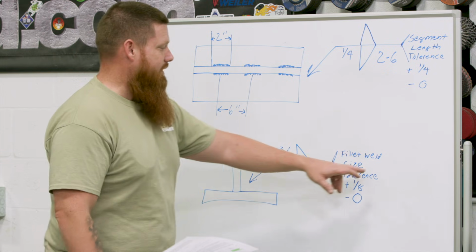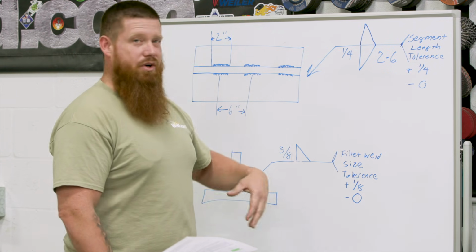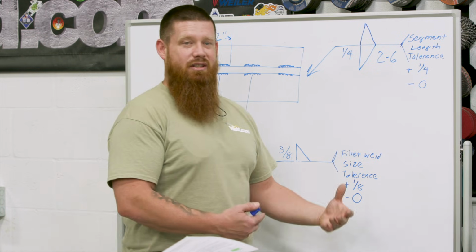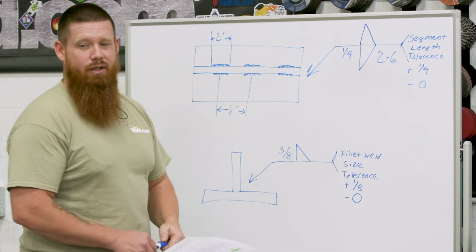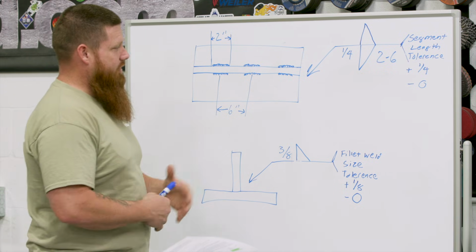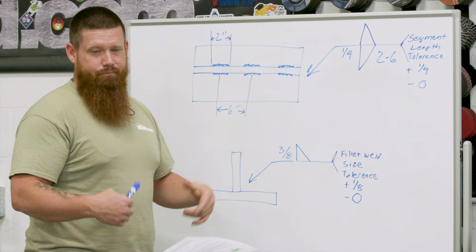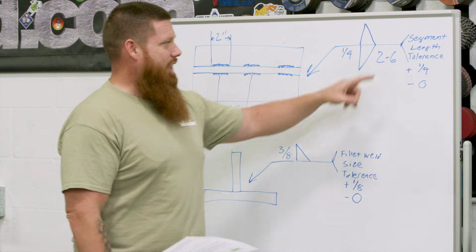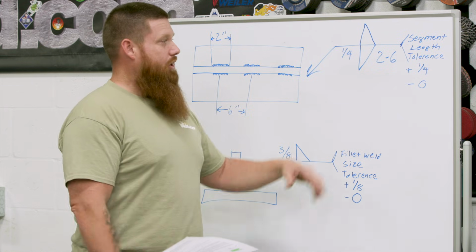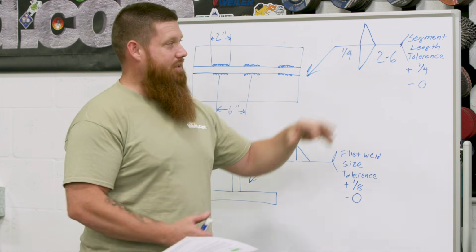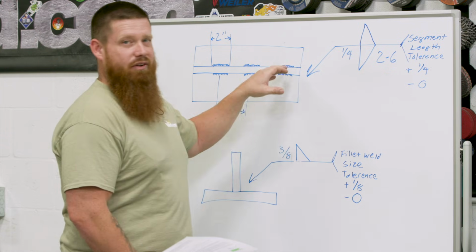So that's pretty much tolerances. They're going to be listed out in the tail. Remember, the tail is where we're going to find special information or additional information that they don't have an appropriate symbol or supplementary symbol for. So that's where we're going to find that information, is in that tail. Let's go ahead. I mean, it's pretty self-explanatory. Now you've been exposed to it, always check your notes section. Sometimes inside the tail of the weld, they could refer you back to a specific detail that's on a different page. So they'll give you that page number in there and that detail number. You'll flip over there and you'll get additional information on this specific weldment.